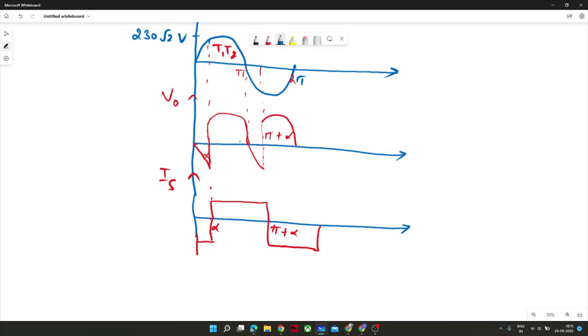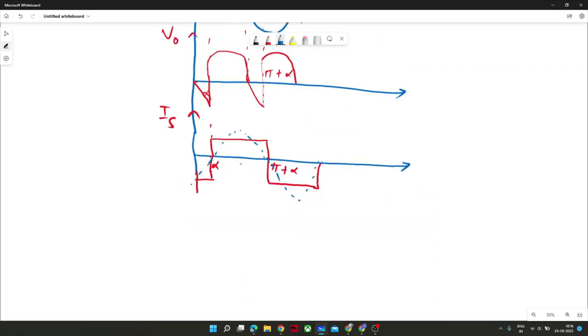So this is a square wave diagram which consists of several harmonics of the fundamental component, and that fundamental component will also have some contribution, and I would say that would contribute majorly in any power electronics converter, and it should contribute majorly because that is the point of using any DC to AC or AC to DC converter. So this blue one that you are observing is IS1.